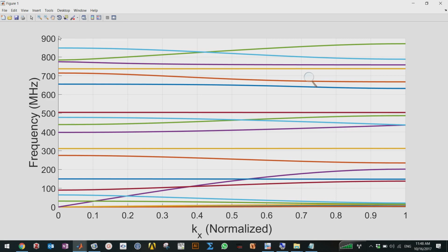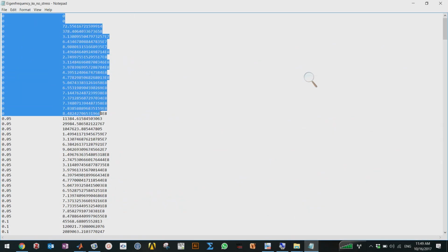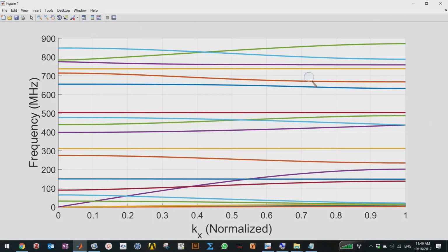So then, you already saw that silicon nitride is a high-stress material, and the stress inside plays an important role because it will affect the speed of sound, your Q factor, and everything. So what we want to do is modify our study, our model, in order to have a more realistic simulation. So what I add here, I will go to study steps.